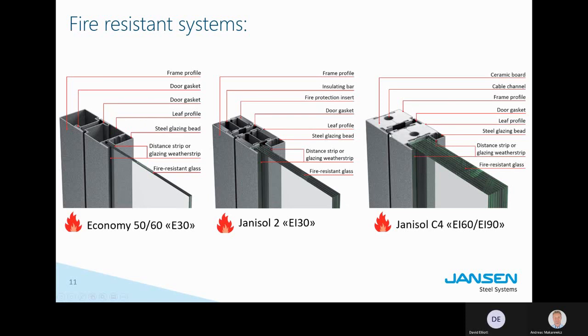What this profile features is, again, a thermal break between the two half shells. And what's different here compared to Yanisol 2, it is fully filled with a ceramic mass. So the cooling function is much greater, much more pronounced. This profile can resist times up to even 2 hours. We're actually testing it for 2 hours sometimes for project solutions. So this is how we handle fire protection.